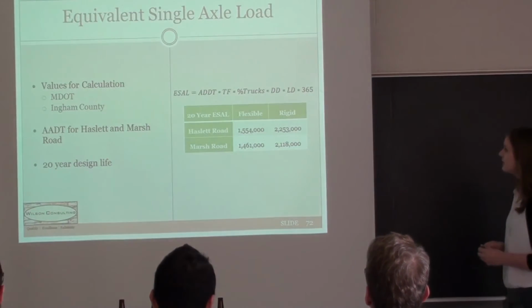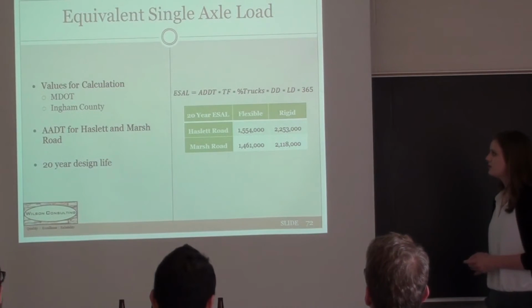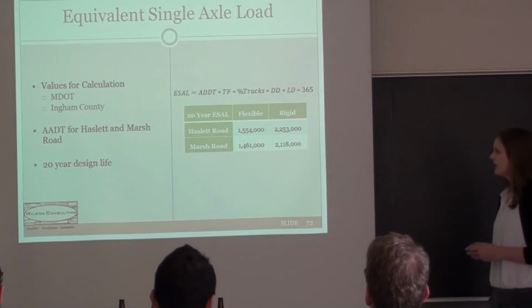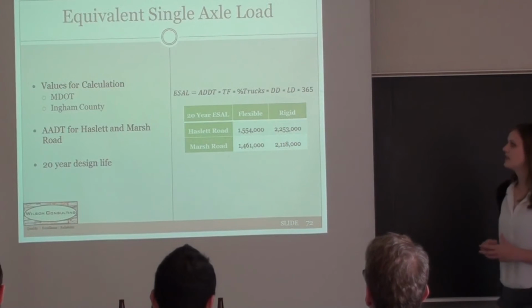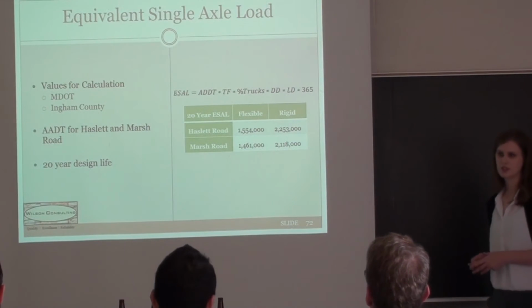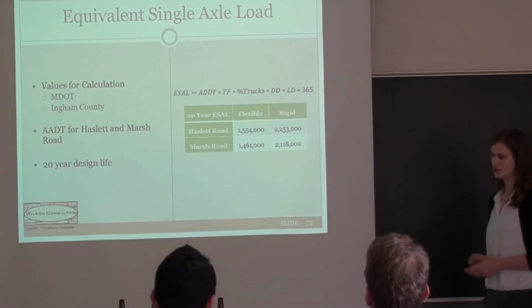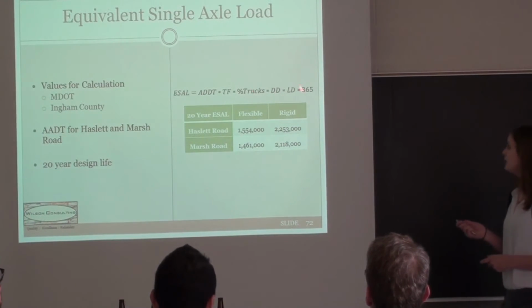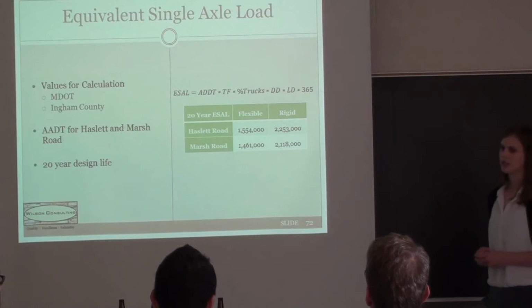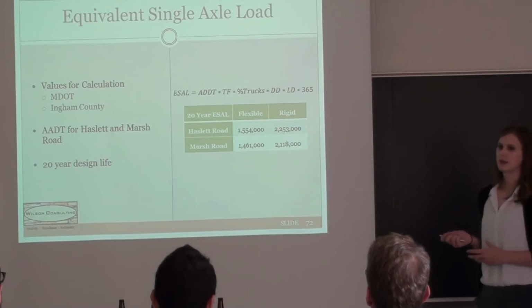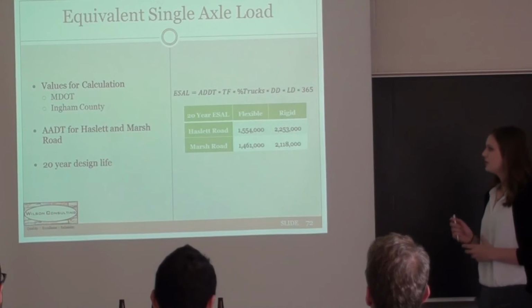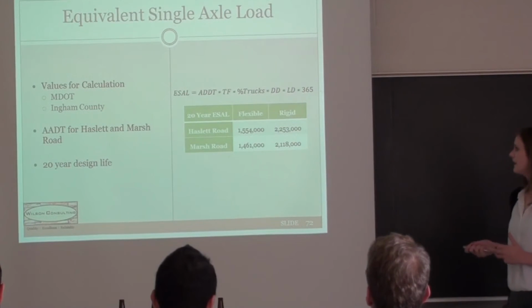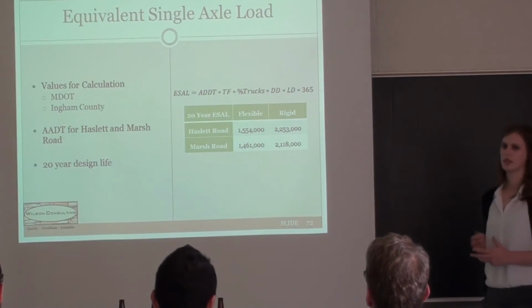So the equivalent single axle loads, or ESALs, were used to determine the different ESALs on site, and this was done using Ingham County Road Commission's traffic counts provided by our transportation specialist, Lindsay. Also, the MDOT values were used in this equation to get the 1-year ESAL. This was then multiplied by the growth factor to design for a 20-year design life, and values found are shown here for both flexible and rigid pavements.